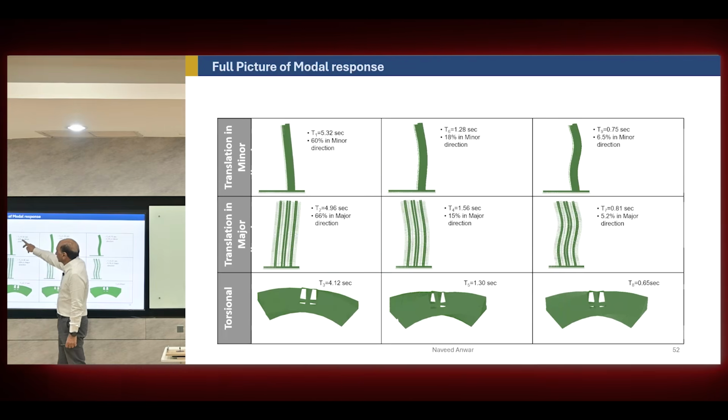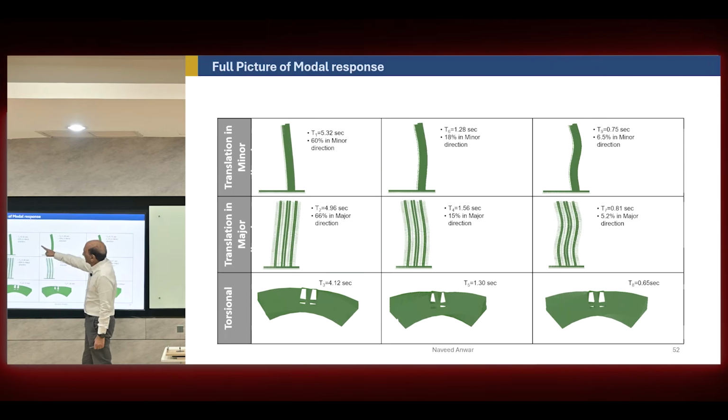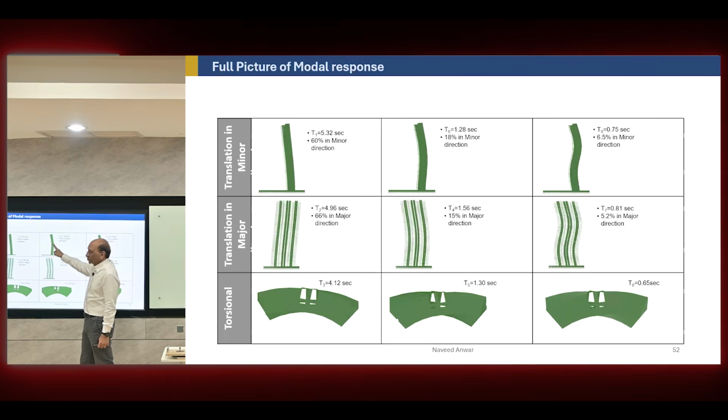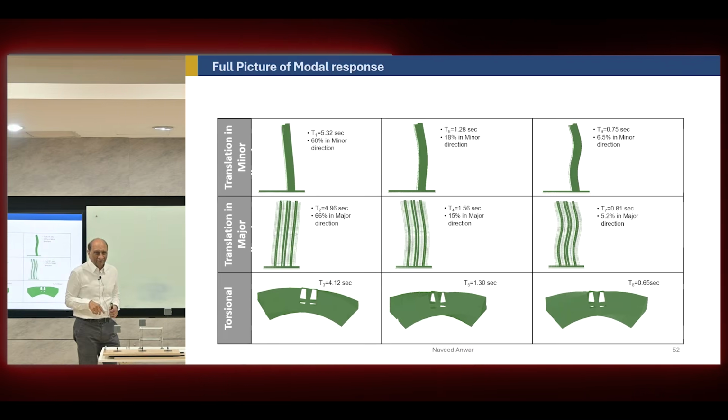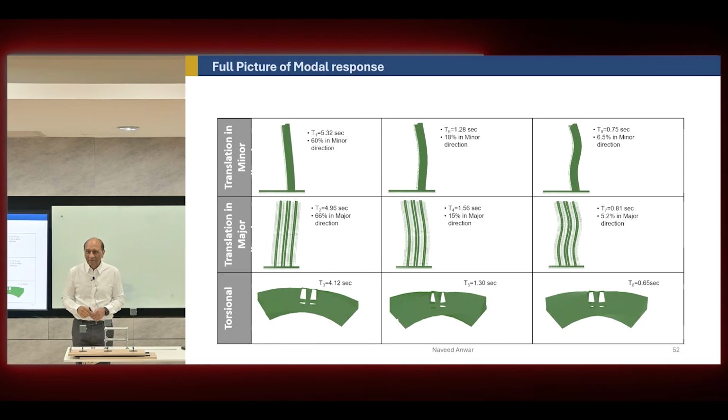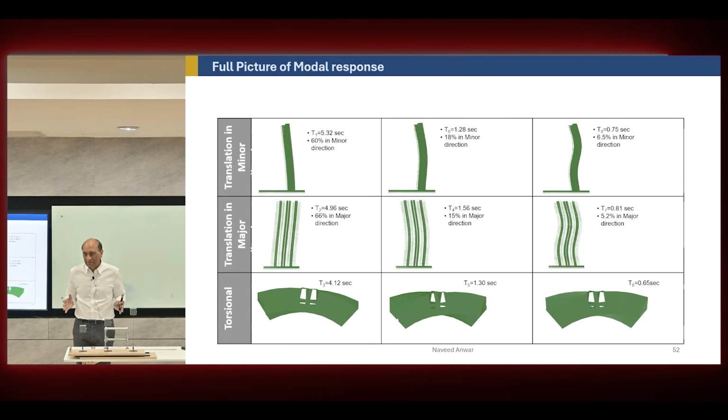And in this direction, we are looking at mode, period, and mass at the same time. The next period in that direction is number 6, not number 4. So this is 1, 2, 3, 4. They will not be arranged in order anymore on a real building. They will depend on how they are activated.